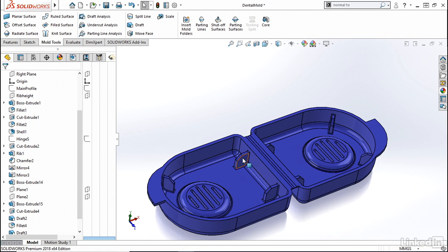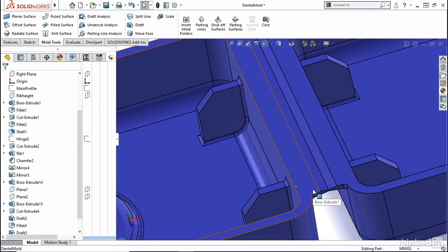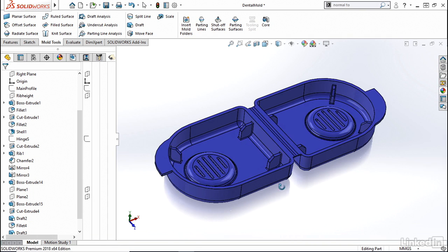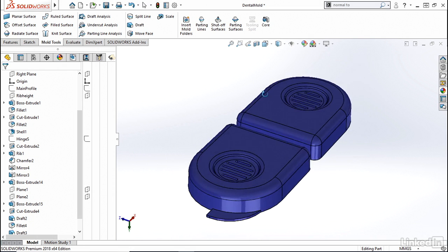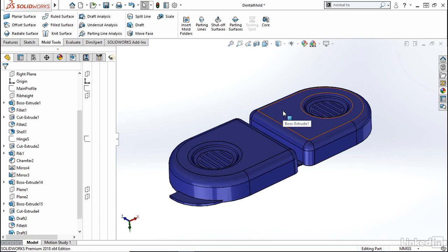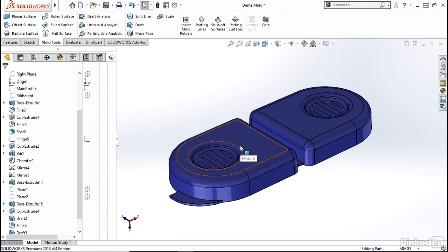I can see that there aren't any spindles or parts that have super inconsistent thickness, excepting of course this living hinge, which will enable the case to open and close with the flexibility of the plastic. In this instance, I would model this in this upside down orientation and add funnels and vents to the bottom of the case. That way, gravity could aid my process. In injection molding, this would likely call for 2 injection sites, one in each main mass.